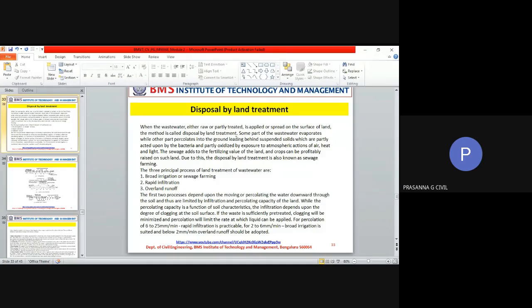You know all the series of layers of soil, and you will make percolation pits also. We will talk about this at a later stage. If you are filtering this water through a layer of aggregates, gravel, sand, etc., and then allowing it to seep through the ground, as it filters through the ground, all the remaining contaminants will get trapped in your media of soil and sand, and this water will get a chance to mix with groundwater.